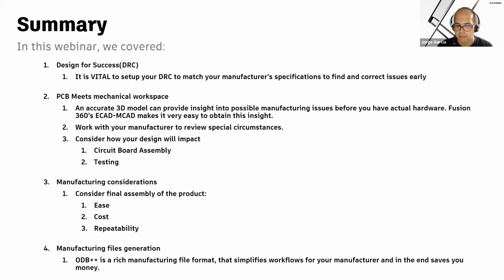And then finally, we saw how ODB++ files can be super helpful because they bridge the gap between full IP reveal with Eagle files versus no IP reveal with Gerbers, and then giving a more usable data structure for manufacturing.